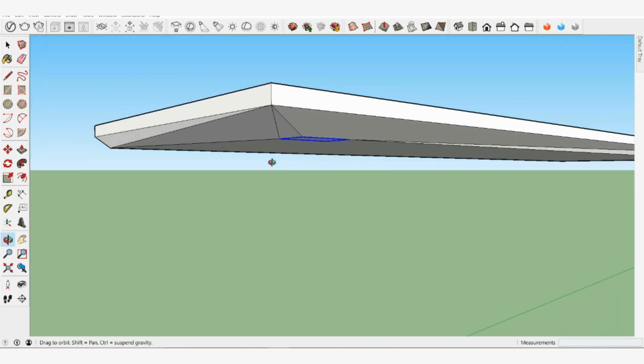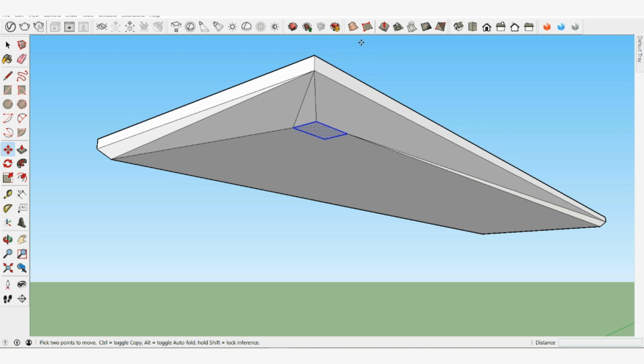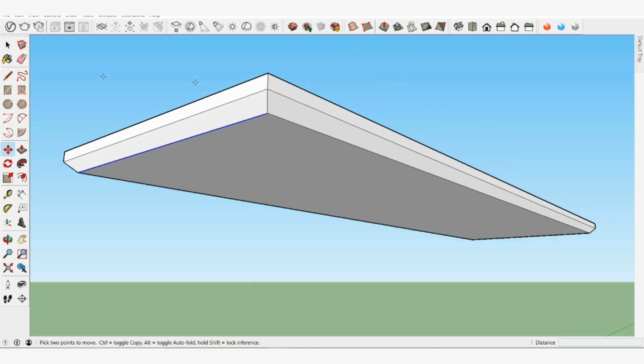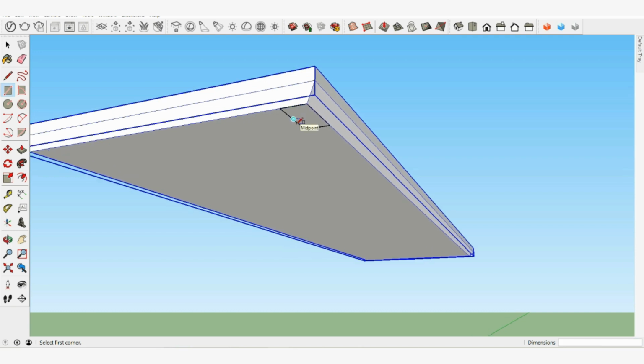To see this in action, undo the rectangle using Ctrl+Z on a PC or Command+Z on a Mac. Then triple click to select the whole tabletop. Right or context click on the top and from the submenu choose Make Group. A new bounding box is shown around the whole top and it now behaves as a single unique entity. Draw the leg rectangle again, make it 2 inches long, 1 inch deep from the corner, but this time it won't merge with the edges. So if we wanted to move it around, we could easily do so.